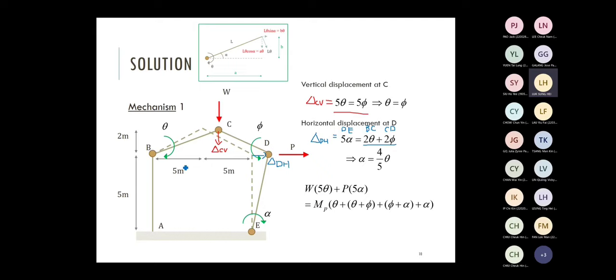And you can see that again, I try to consider plastic work first. I believe that plastic work is easier to obtain, and you just need to count the number of rotations, I mean the total plastic rotations for each hinge.